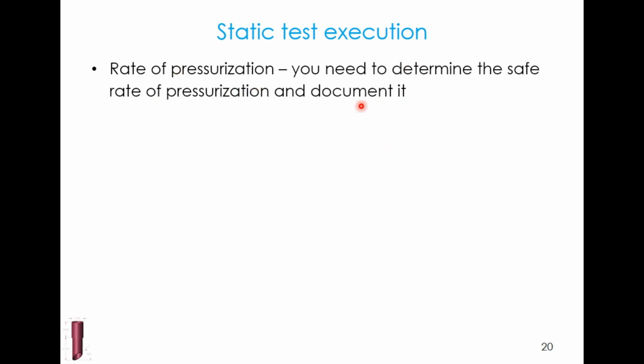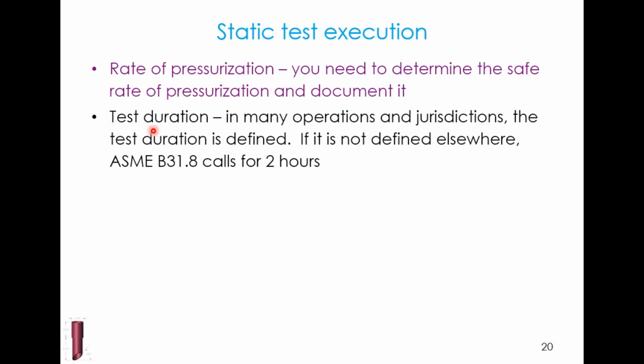When you're executing any static test, you want to think about the rate of pressurization. What's safe? If I'm pressurizing too fast, I can prevent metal stresses from equilibrating and can fail a pipe that wouldn't have otherwise failed. Test duration. In many operations jurisdictions, the test duration is defined.